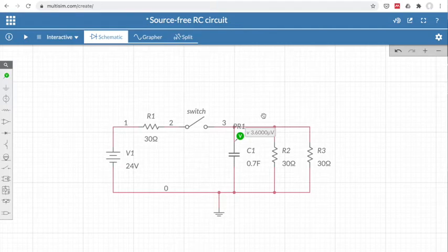0 volts. So I've assembled this circuit, and just a reminder that when you run a simulation using Multisim, you need to connect a ground for the entire circuit. Otherwise, the circuit will not work. So let's do this. Once I press play,